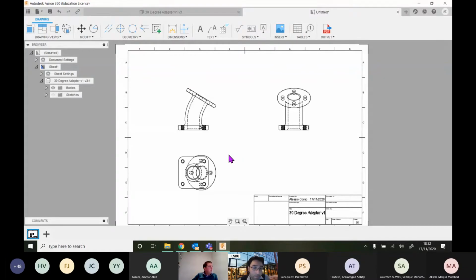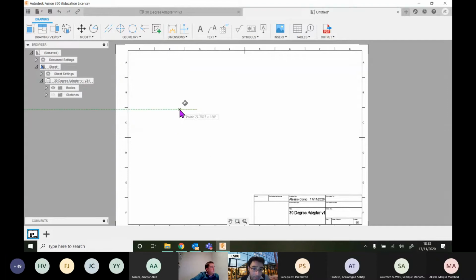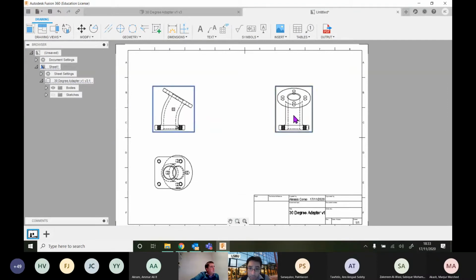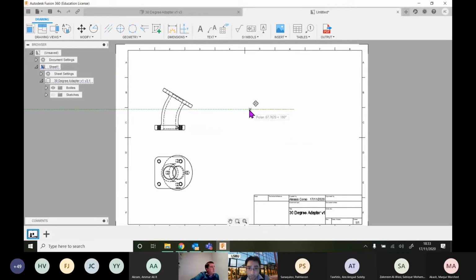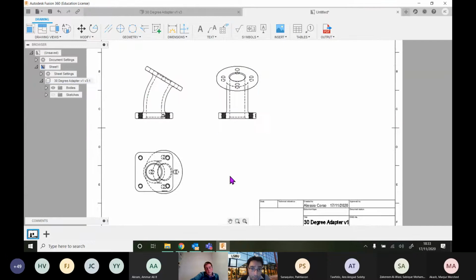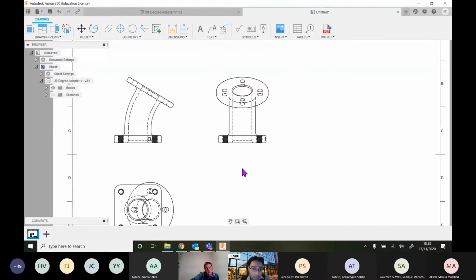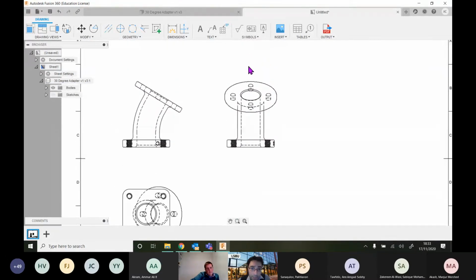we've got the option to create section views, which is where we cut through our parts. So we can do that using a section view. So let's do that next, just to remind you of how we create a section view. So let me move these views over to the left. I'll move this view over to the center, and it might be useful to create a section view that's down the middle of this view here.